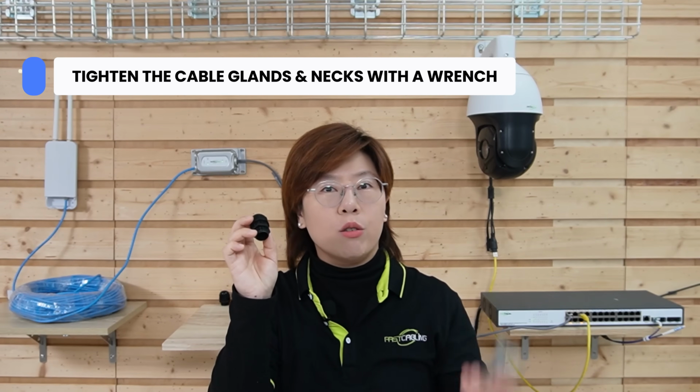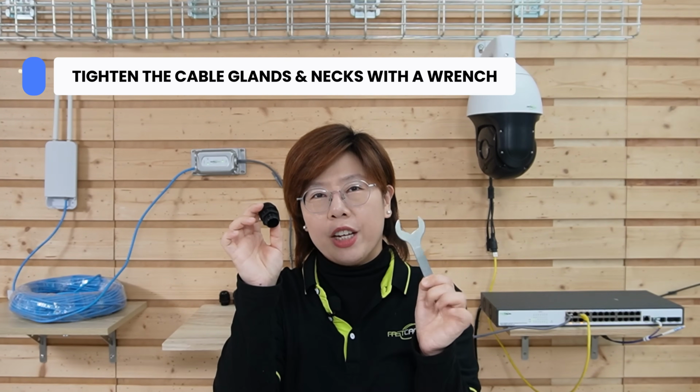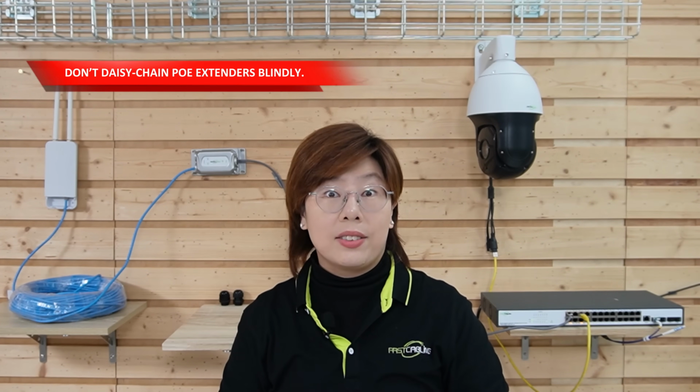Also, tighten the cable neck and gland using a wrench, so the rubber seals compress around the cable jacket. And don't daisy chain extenders blindly, because every hop introduces some loss and consumes power from the PoE budget.